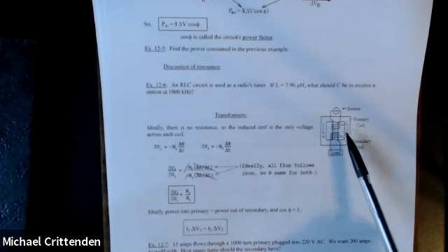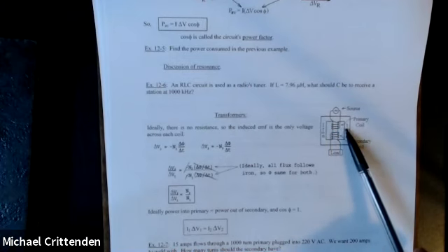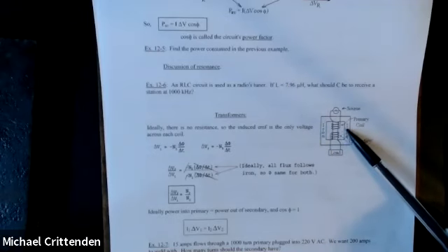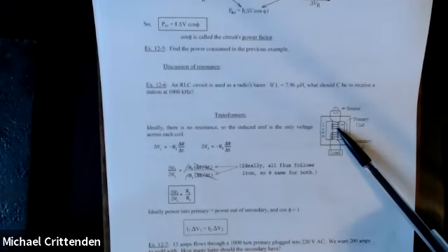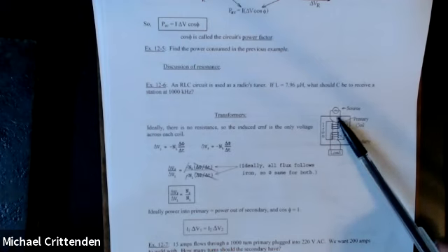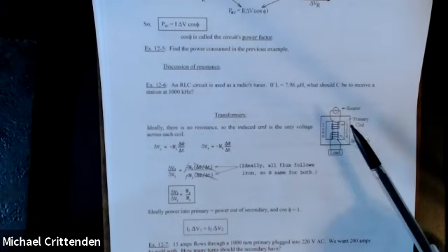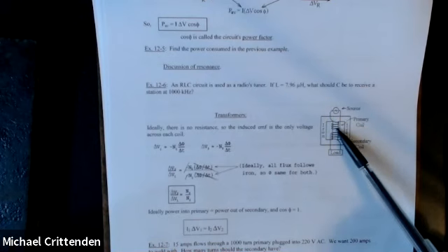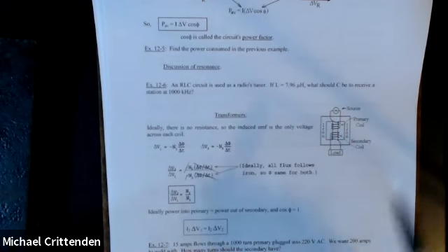So we're going to assume idealized conditions, sort of like frictionless surfaces when we were covering mechanics. We're going to assume resistanceless wire that this coil has been made out of. So therefore, there is no potential difference due to Ohm's law, because we're saying the resistance is small enough to ignore. The voltage across this coil is a self-induced voltage from Faraday's law.